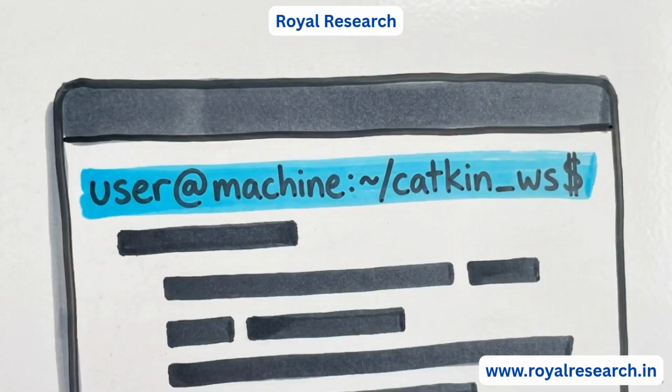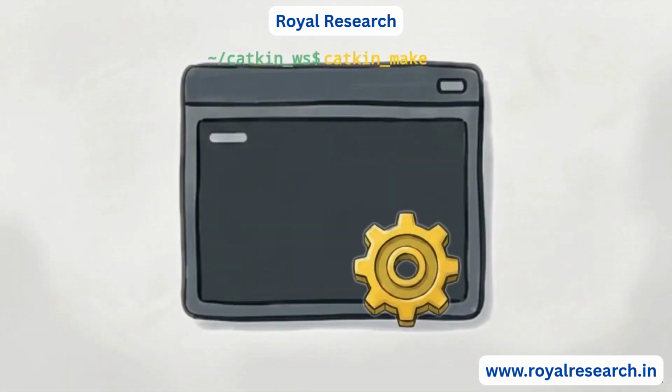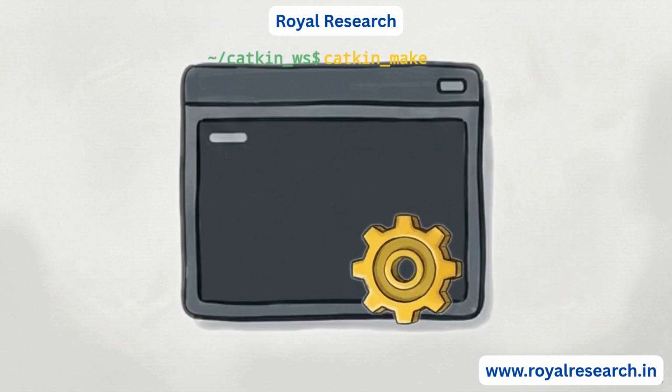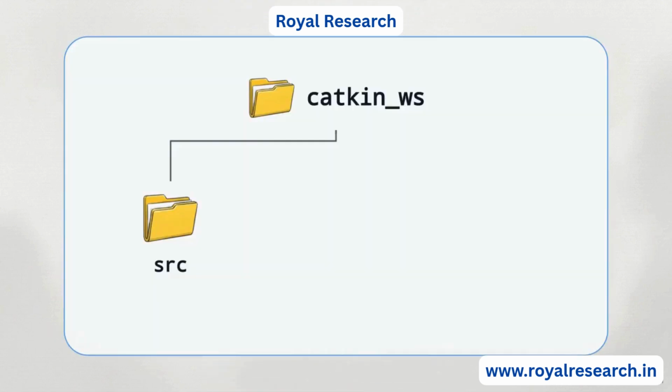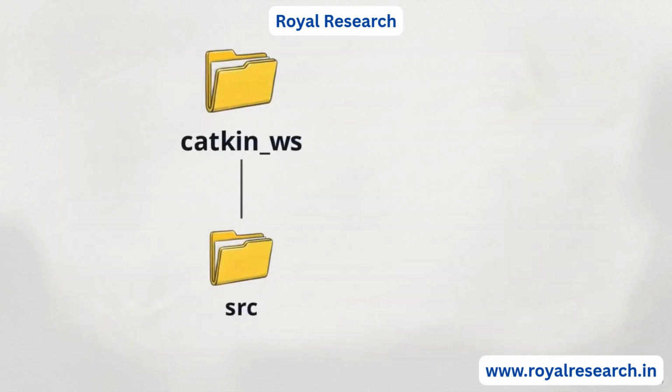Once the directory exists, type cd /home/catkin_workspace to navigate your terminal directly into that new workspace root. Now type catkin_make and hit enter. Your terminal will immediately output a rapid scroll of text as the system generates the build and devel directories required for code compilation. Pay close attention to where you execute that command.